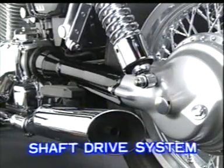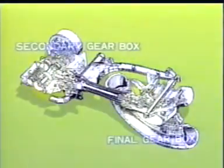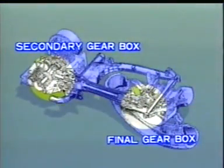A system in which the rear wheel is driven by means of a shaft rather than a chain is called a shaft drive system. The reduction ratio in the shaft drive system is determined by the ratio of the number of teeth on the secondary gearbox attached on the engine side and the final gearbox attached on the drive wheel side.